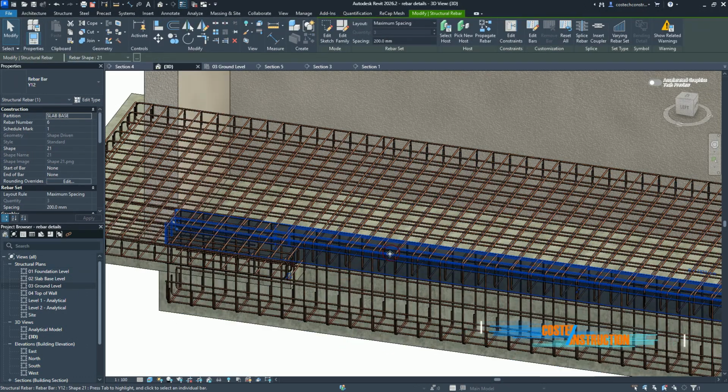So we can select this top rebar, the one which is hooked, one which goes with the beam. Then from here, I will give it a value of W10 for all 10. Then hit apply. Now this one is only applicable at this top rebar set, while in the selection of the slab rebars.